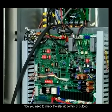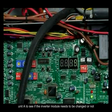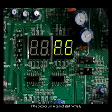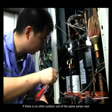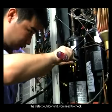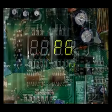Now, you need to check the electronic control of outdoor Unit A to see if the inverter module needs to be changed or not. If the outdoor Unit A cannot start normally, that means the compressor has a malfunction and needs to be changed. If there is no other outdoor unit of the same series near the defective outdoor unit, you need to check and repair as follows before changing the compressor.